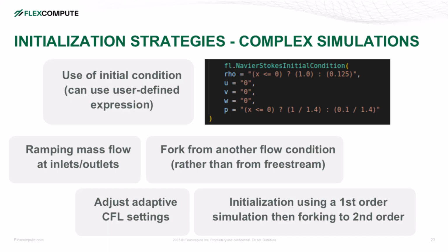If a case diverges repeatedly and you cannot resolve it by adjusting mesh, boundary conditions, or initial conditions, you can also rerun the case and stop a few iterations before the divergence point. Export the solution fields at that stage and inspect flow variables and mesh quality around the problematic region. This often reveals the underlying issue.